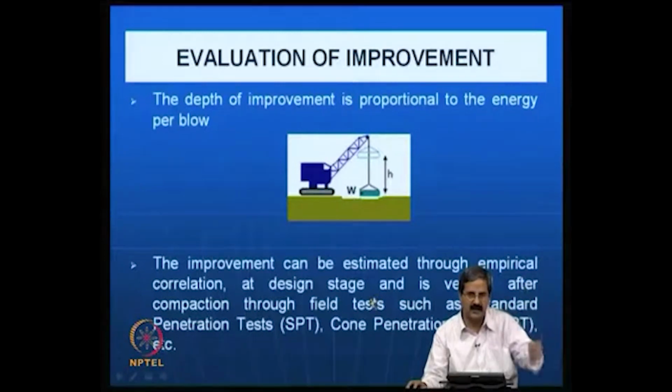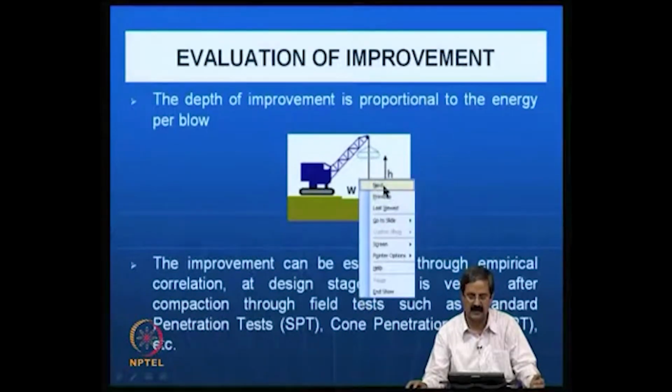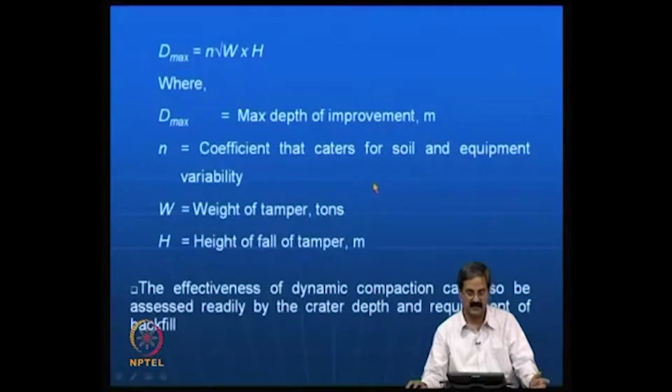You take SPT values or cone penetration values up to 20 meters, then measure them after improvement. So, that is the only way of improvement one can see correctly, like otherwise it becomes very difficult.